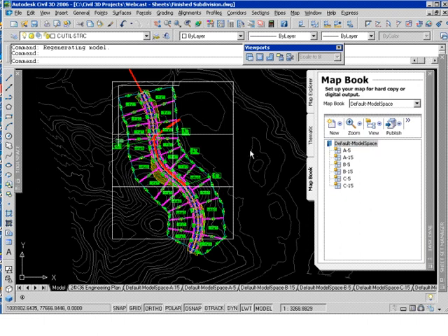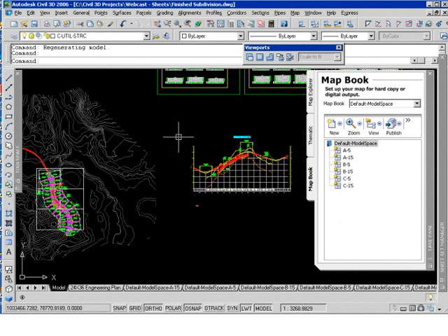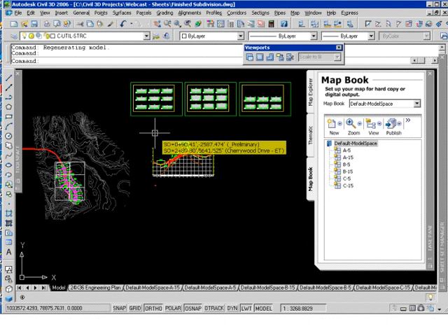The other thing, as far as working with map books, let's touch on some of the holes in Civil 3D for sheet layout. We can do cross-section sheets in 2 different ways here. We saw it with Sheet Set Manager. We saw it with map books. Well, not really, but you'll have to trust me on that one. And we also saw it for site plans. So whether it be a subdivision design or a large mall or some sort of site design where you need to cut up your sheets, but they're all sequential, they're on a grid format, MapBooks is really a powerful feature to allow us to automatically lay out that grid and automatically cut our layouts.